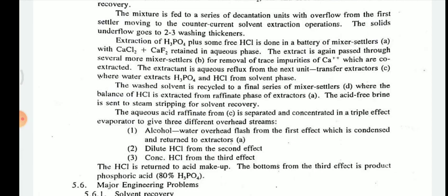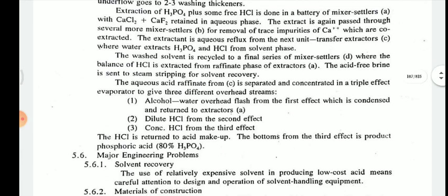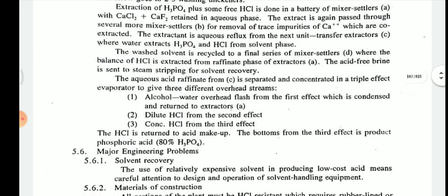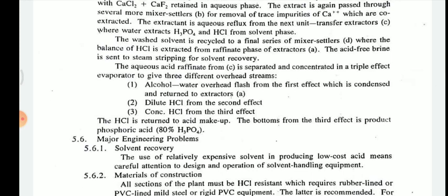Okay, and the last extraction process uses a reflux from heat transfer extractors, where water extracts H3PO4 and HCl from the solvent phase. Then the wash solvent is recycled to the final series of mixer settlers, and that will be the balance of HCl extracted from the raffinate phase of the extractor.